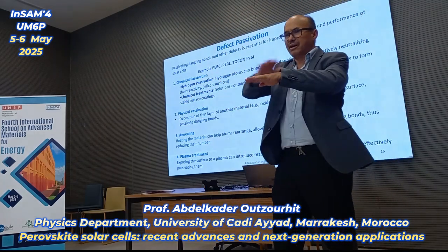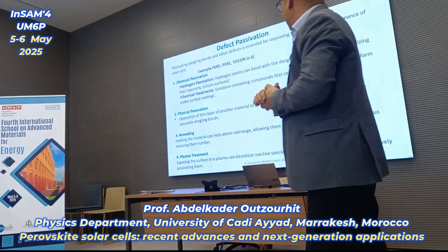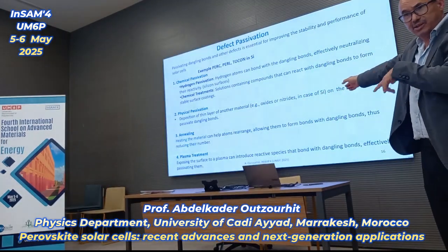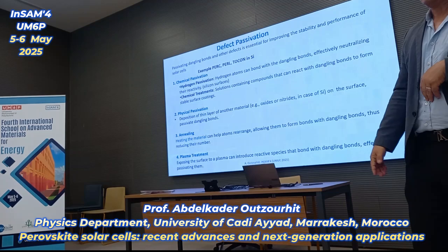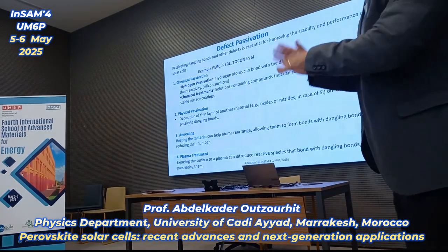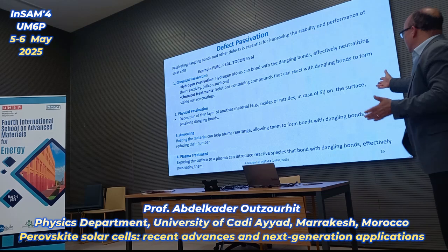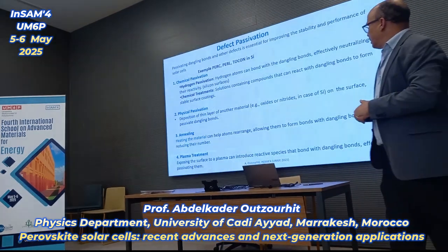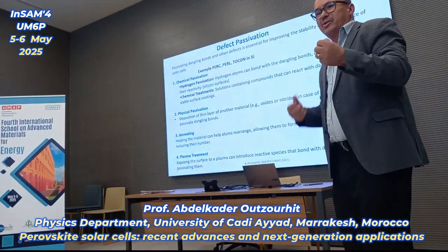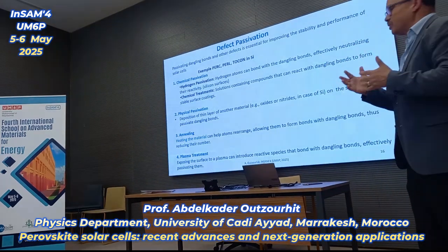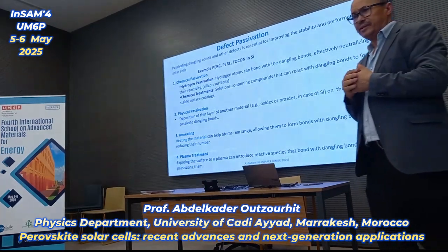Just put a thin layer of some material, an oxide or nitride. In silicon, that's what is used a lot to passivate the surface. You use amorphous silicon or silicon nitride or aluminum oxide or silicon dioxide. You can also try to anneal your semiconductor to remove dangling bonds, because you can create what we call reconstruction of the surface.